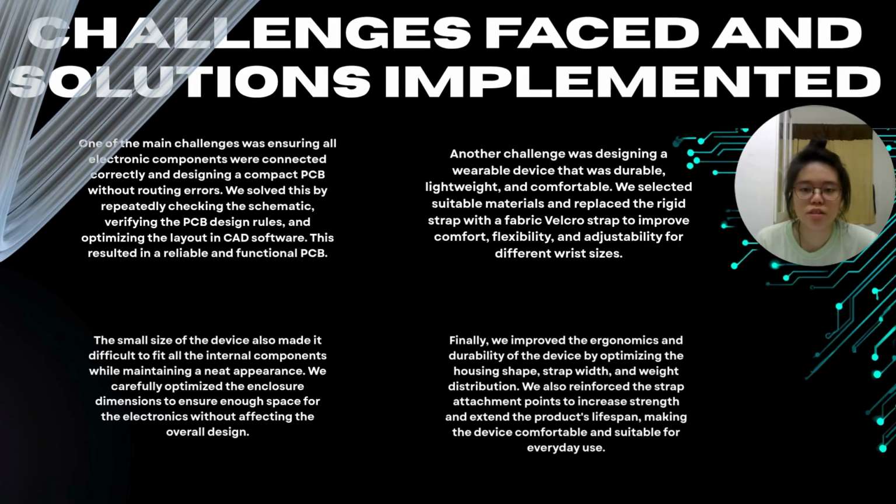One of the main challenges was ensuring all electronic components were connected correctly and designing a compact PCB without routing errors. We solved this by repeatedly checking the schematic, verifying the PCB design rules, and optimizing the layout in CAD software. This resulted in a reliable and functional PCB.